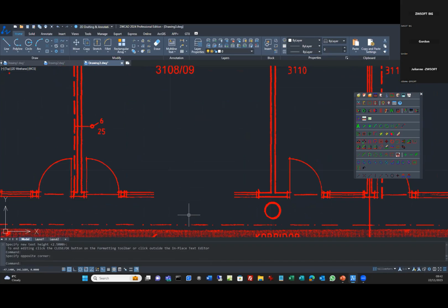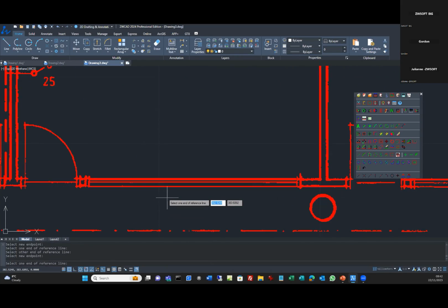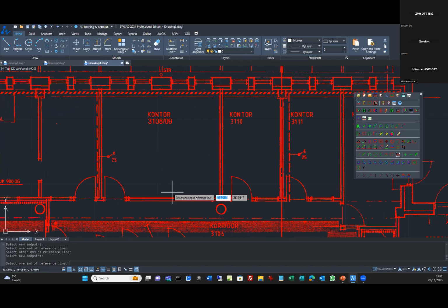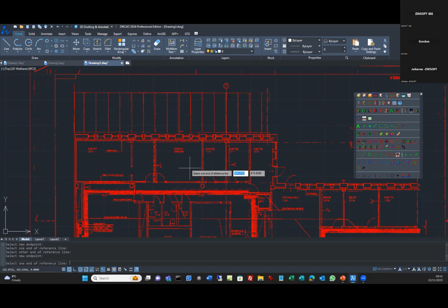Like I say, it's still as a scanned image. I haven't converted anything. And then I can repair my lines in my wall and say, right, bring that across to there, bring that line across to there, bring that line across to there. So you could save that now as a TIFF or as a PDF, and that would be your new change or your new edit to your drawing, if that's all you want to do to it. So, like I say, there's lots more raster editing commands that we can do. But to move on, I'll show you some of the conversion.